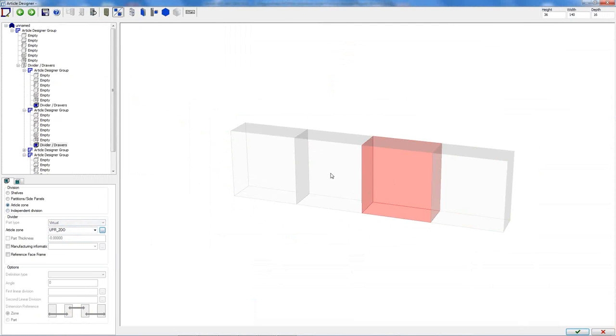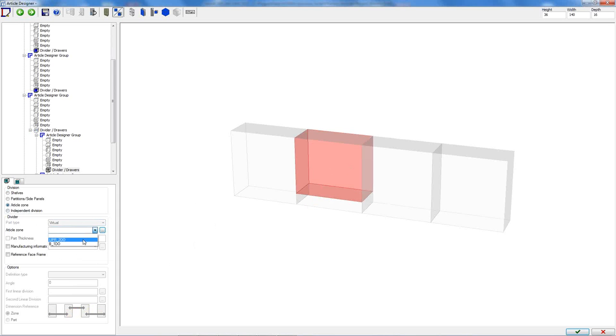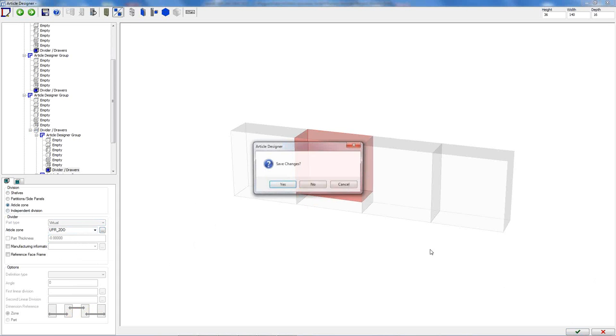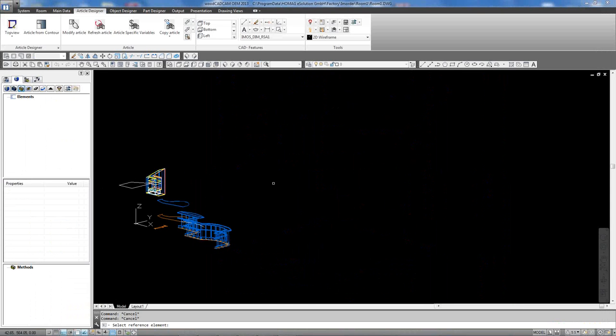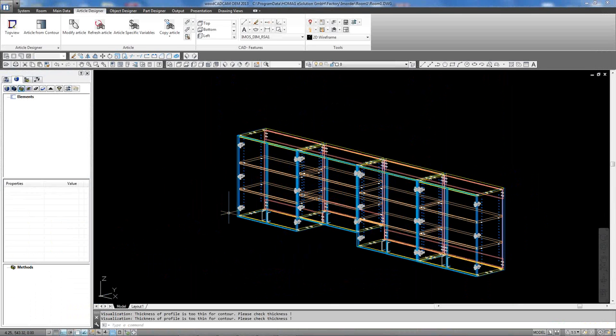And this one here, I need a 6-inch space at the bottom, so I need to split it first. 6 inches to 1, giving me 2 zones. Now put an article in there. On and on, whatever. So now I've got a big area with 4. They're all the same cabinets, but you'll get the idea. Really handy for the case where the architect gives you a wall dimension and wants the cabinets equal. So that works good.